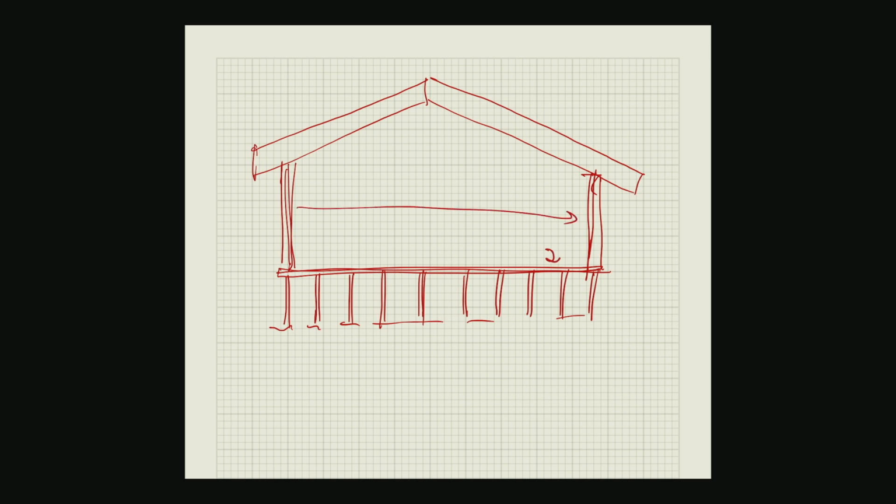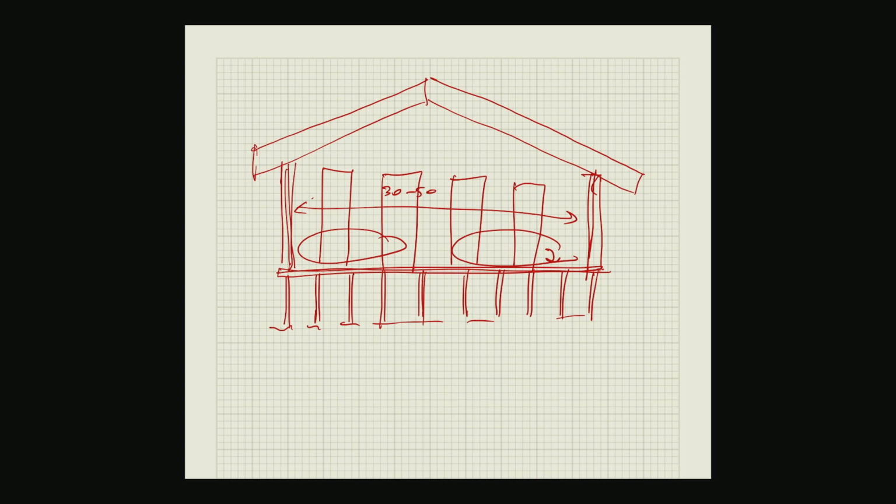Space here is around 30 to 50 meters. Of course, you do not want to have columns in between because you're going to put the stack for the storage, or you want to put the equipment or machines in the factory floor area. So generally there is no column in there, and the roof truss has to span over 30 to 50 meters, which is quite challenging.